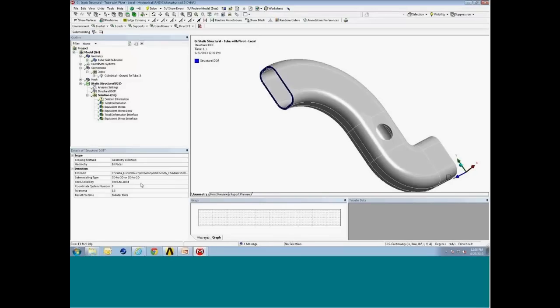Next thing you want to identify is the submodeling type: 2D to 3D, 3D to 3D. In this case, with this 3D geometry, we're specifying a shell to solid connection. And so this is what triggers transferring those shell rotation degrees of freedom over to our solid finite element model. Once you have that set up, you can go ahead and post-process as you normally would in a submodeling procedure.